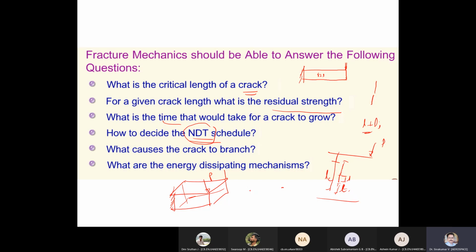We know the severity of the location, structure and manufacturing process, so maybe every 100 cycles of the aircraft, I can take up one particular component and test it for NDT. If I find there is no crack formation, I may refit it into the aeroplane. So how can I issue that schedule? How can I know that schedule, unless I have analysis information on it? That is what the fracture techniques give.